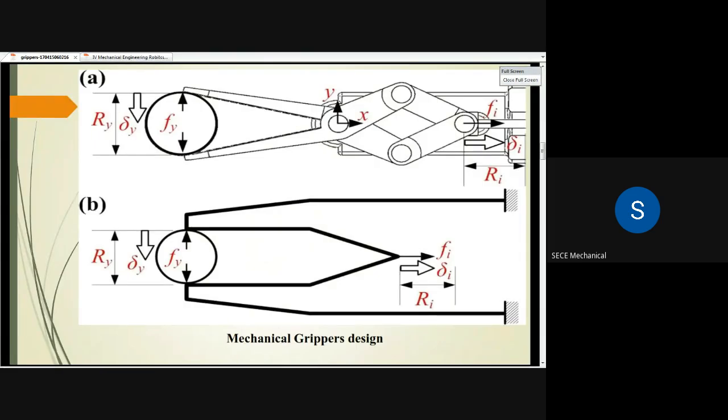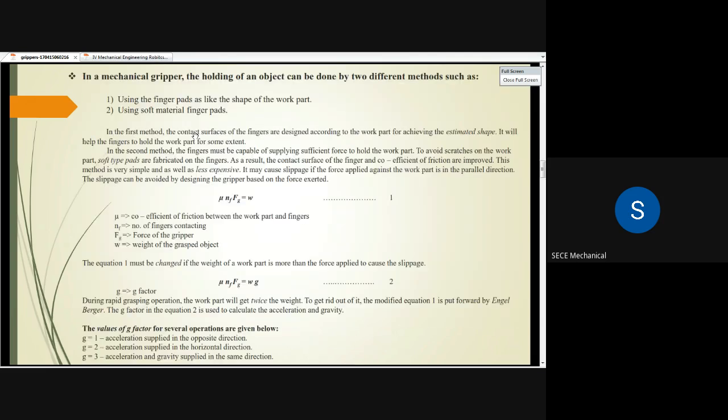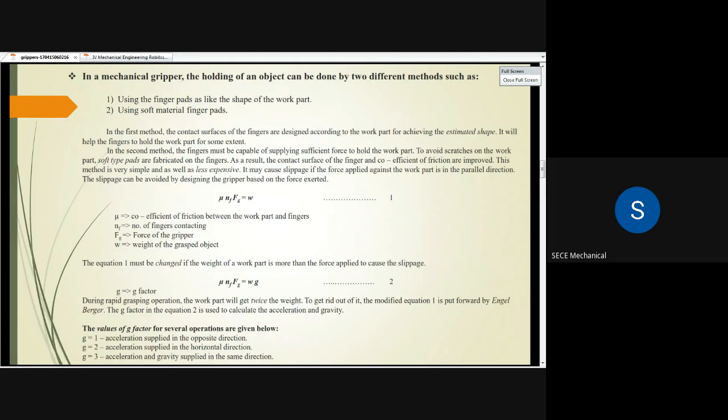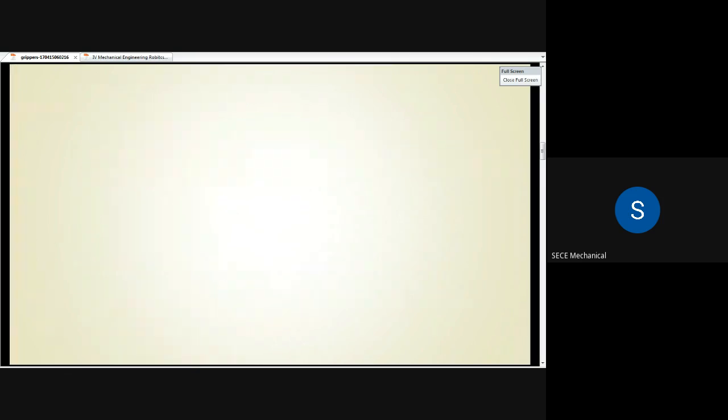Look here. This mechanical gripper also has an end flange. At the end side of the end flange we have pivot based linkages. This is called pivot based linkages, while these are called fingers. We saw the name fingers in the last class. Based upon the actuation of the pivot based links, the fingers can hold down the object. I will come back to the calculation method, the force analysis literally required to hold down the material.